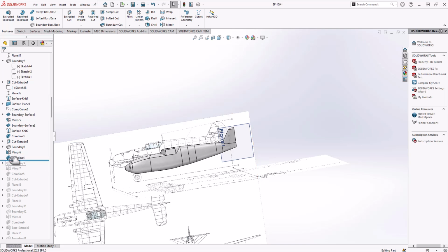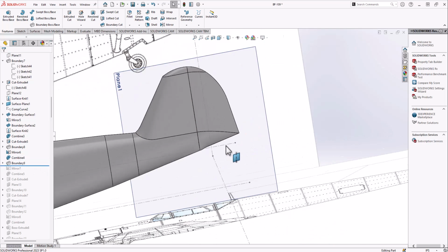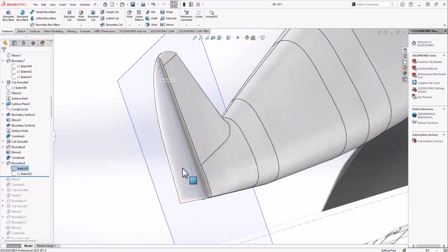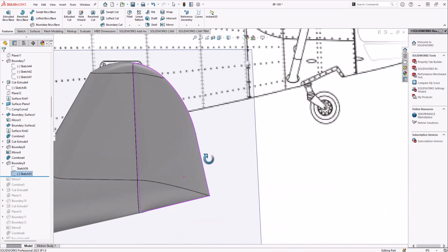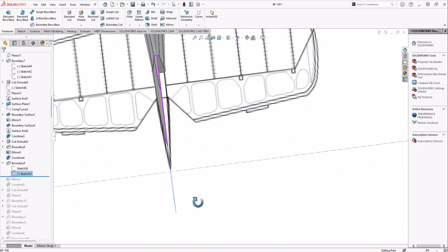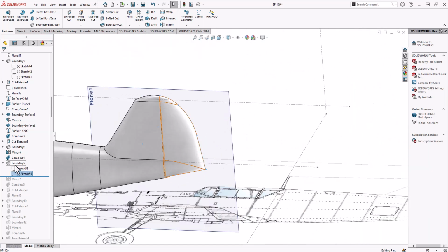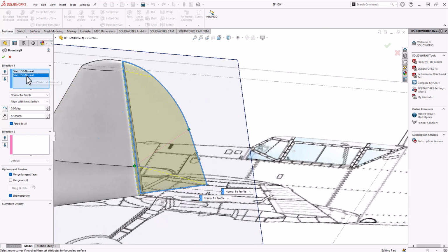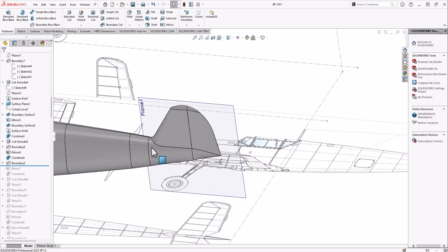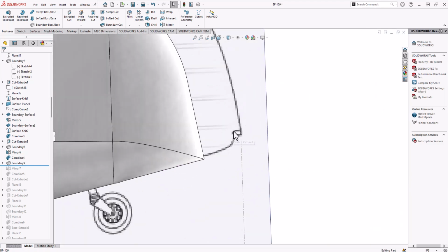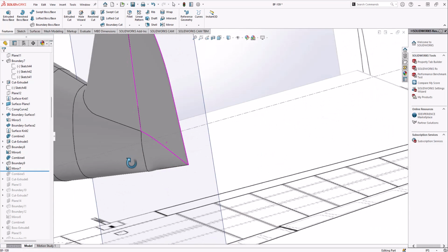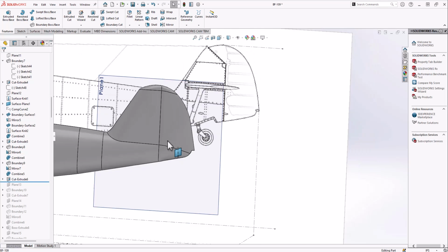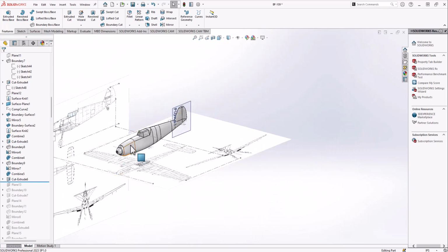Then this next section I believe is doing the rear part of the tail. So it's pretty straightforward. I take the half of the view, so this rear section, and then I have the inner plane, and I just do the boundary between the two, and there shouldn't be any guide curves on this one. And it's normal to profile on both, for the reasons I've mentioned previously. So that's the tail there, and you can see there's still some geometry missing. So once I mirror this and combine it, then I just subtract out that little detail to get the shape looking right.